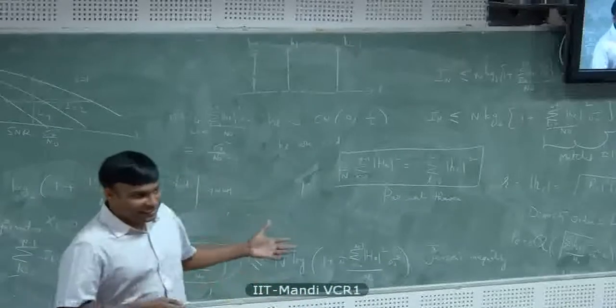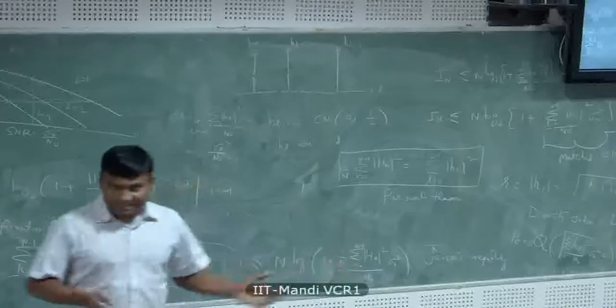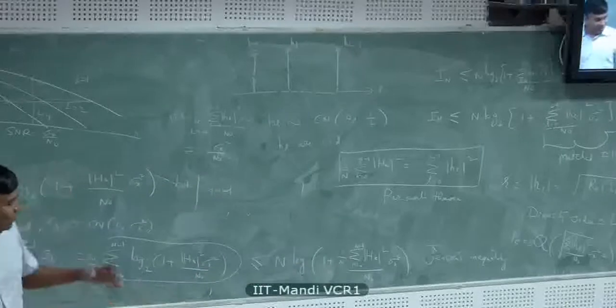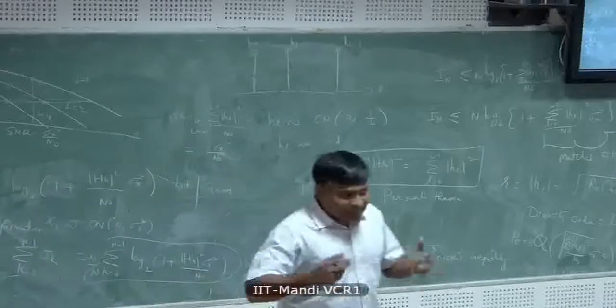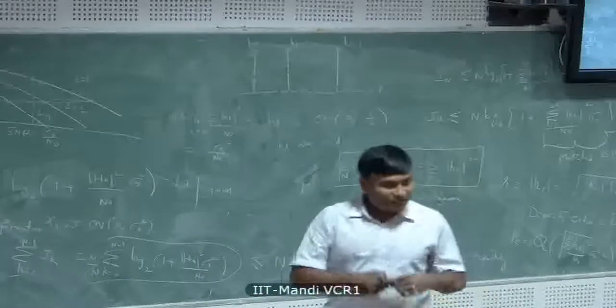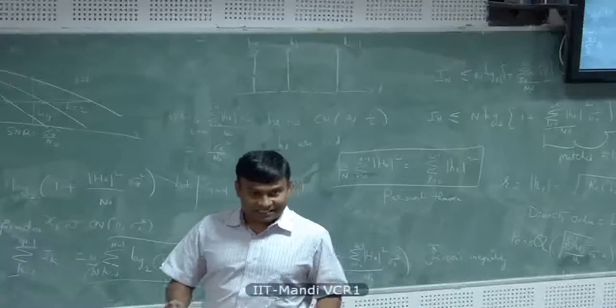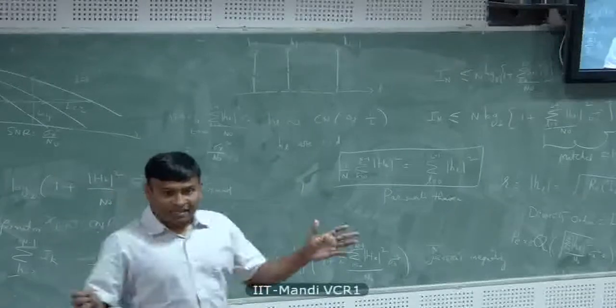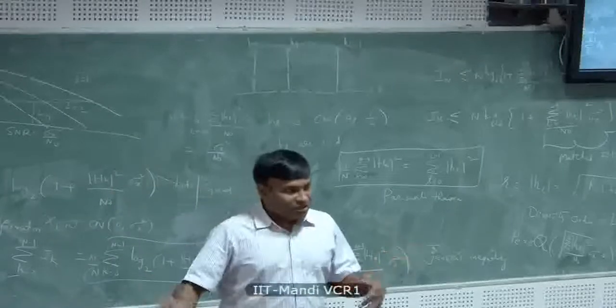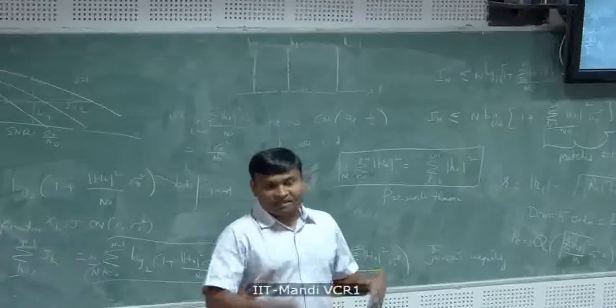We're talking about diversity, but not antenna diversity or MIMO, but rather the diversity from the point of view of what the channel offers, what is already there in the channel. If there is plenty of diversity, exploit it. Narrowband systems need multiple antennas to give you this extra diversity because the channel didn't give you enough diversity, since it was a narrowband system.